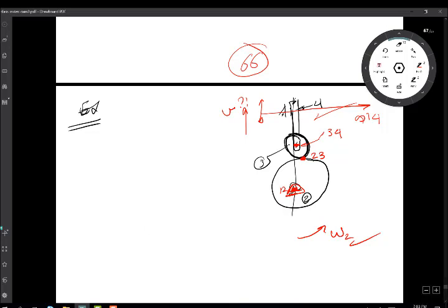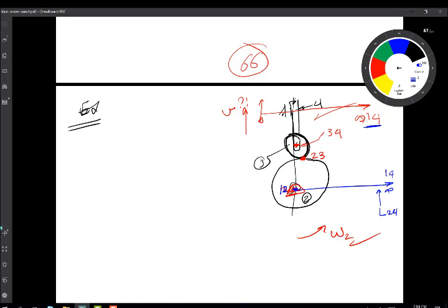So now the straightforward one at the start, I have here point 1, 2, and I can connect it to 1, 4 at infinity. So draw parallel to 1, 4. So now the two numbers, the common number is 1, the missing point is 2, 4. So this will give me a locus for 2, 4, right? So 2, 4 should fall on this line. I need another locus for 2, 4.